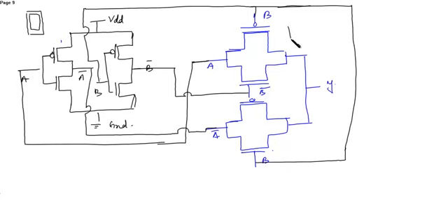But over here you will take the N-well as this, and the P diffusion inside it. Okay, so you can understand, if this is in this format, then this will be the layout, and if this is in this format, then this will be the layout. So you can take the layout from the twisted schematic, which is a bit easier.